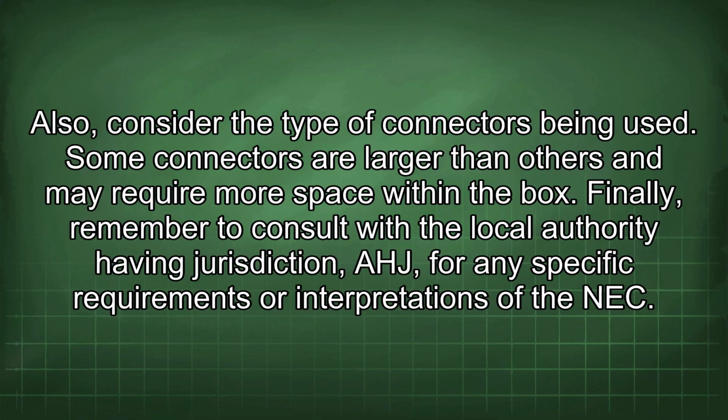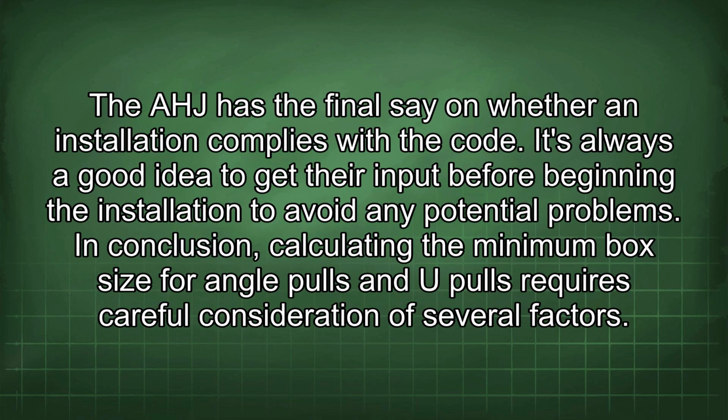Also, consider the type of connectors being used. Some connectors are larger than others and may require more space within the box. Finally, remember to consult with the local authority having jurisdiction, AHJ, for any specific requirements or interpretations of the NEC. The AHJ has the final say on whether an installation complies with the code. It's always a good idea to get their input before beginning the installation to avoid any potential problems.